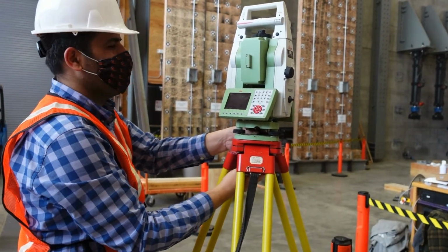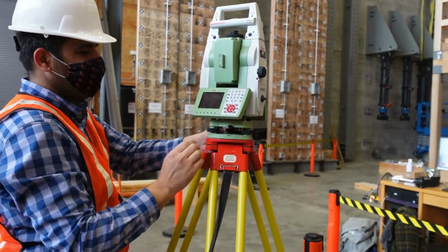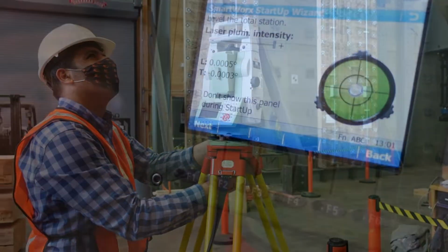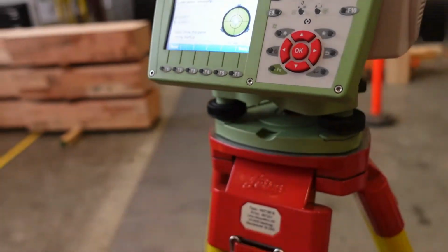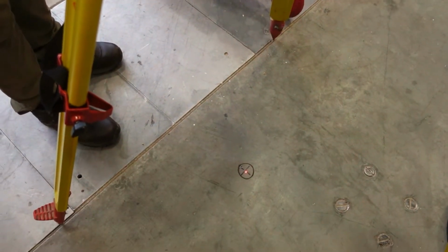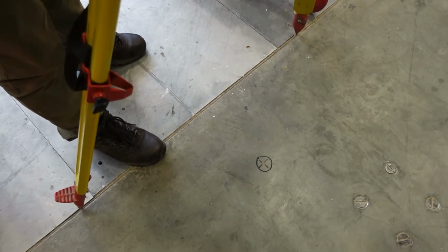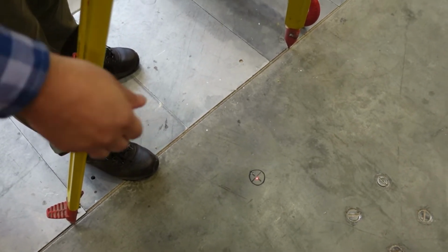Once the targets were located around the experiment, it was time to start the survey with the total station. We set up the coordinate 0 right below the total station, as you can see in the black circle, and it was necessary to level the robot at the same time, to center it using the laser inside control point 1.